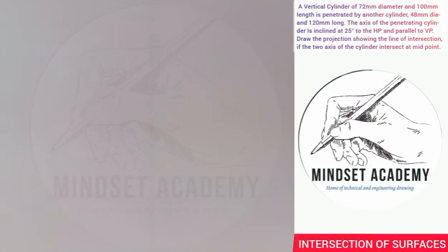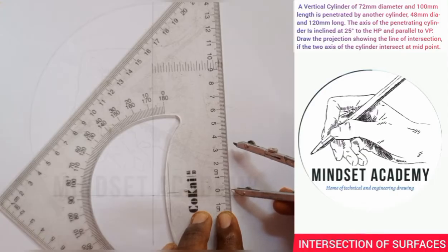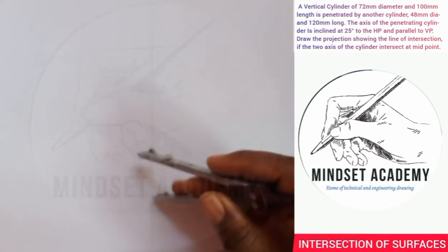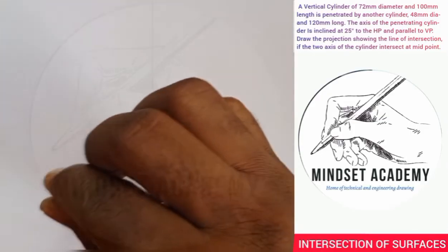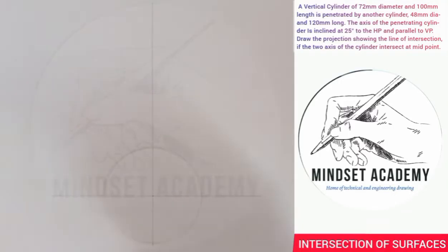So we'll start from the plan. Since we are told it is a cylinder, it means that the plan will be circular. And what is the diameter of the plan? We are told it is 72 millimeter diameter. So I'll measure half of 72, which is 36, and I'll place it at the center here, where I'm going to draw my circle representing it.